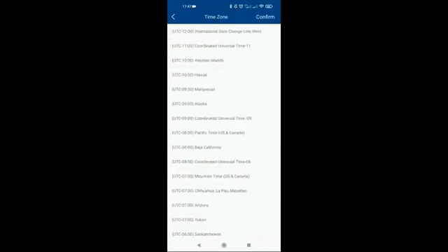What's also interesting, you can choose the time zone here. Maybe you will say, okay, it's not important for me if there is a wrong time in the app, but if you're using the blueplanet web, the inverter will send all its data packages with the timestamp that's chosen here. It's important to know that with default settings, the UTC 0 option is chosen.